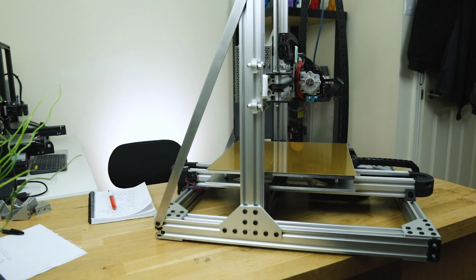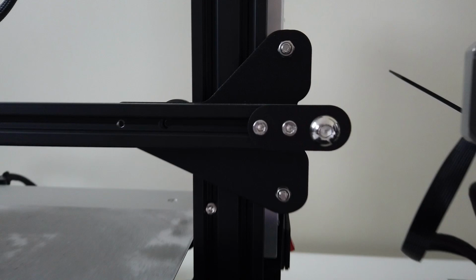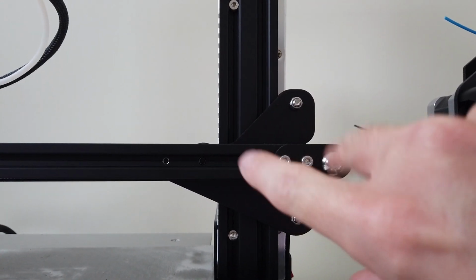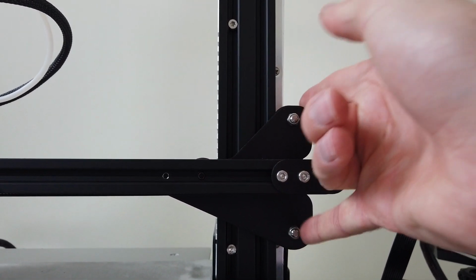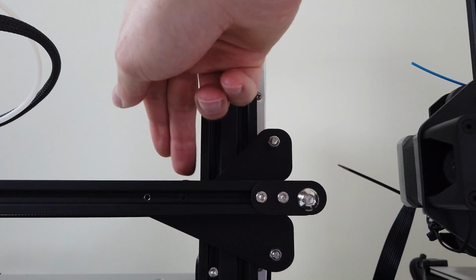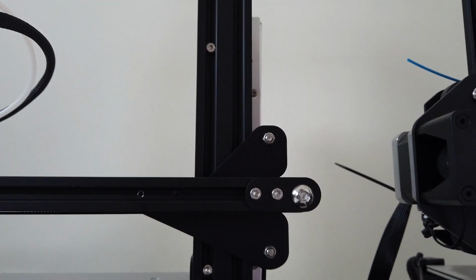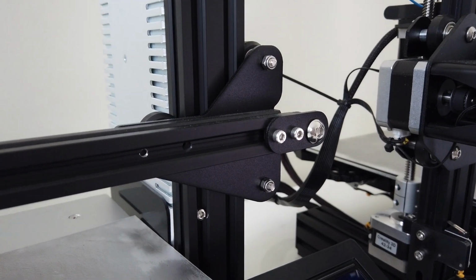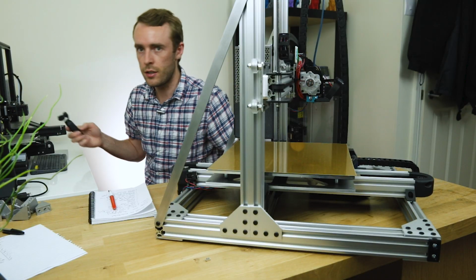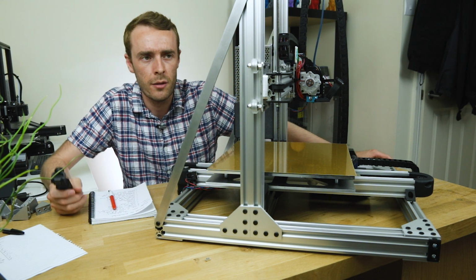So you may be aware of maybe the Ender 3 style printers, which you can't see. The Ender 3 has this kind of arrangement. It has 1 wheel here, and then 1 here, and 1 here. So a total of 3 wheels, and that makes it really easy to set. These 2 are fixed, and you just change the distance between, basically you're setting the width that wants to grip by just changing the eccentric nut on here. That's how the Ender 3 does it, just a 3-wheel system. And it uses the same on the carriage and everything, and that does make it really easy to set. But obviously, with only 3 wheels, you're limited to the amount of load you can carry. With the Ender 3, it's fine, it's just a small printer. But this is quite a lot larger.